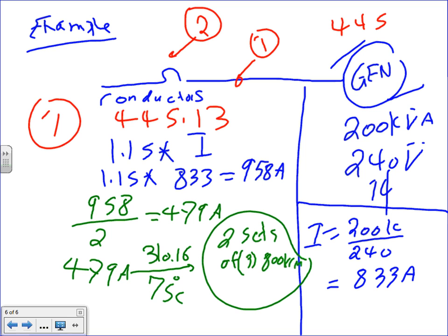Any question, guys? Holly, how much current can 800 kcm carry? 490. Okay, so we have enough room in that one. Any question, guys, about the conductor? Full load amp times 1.15. Done. We parallel just because it's too big. Had this been a 20 kW, you don't have to do anything. You just go all the way.